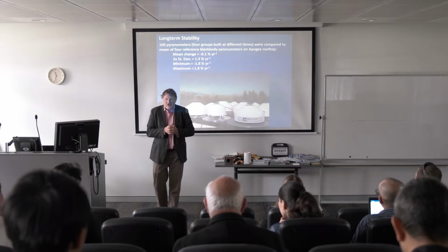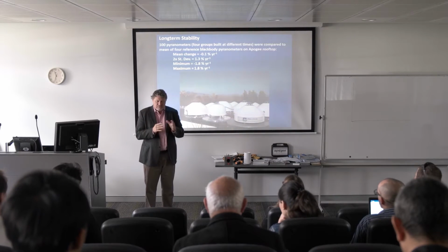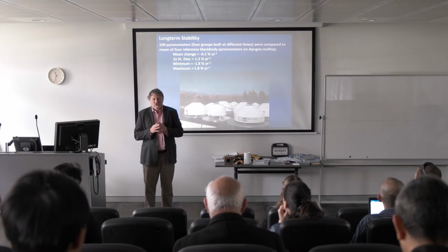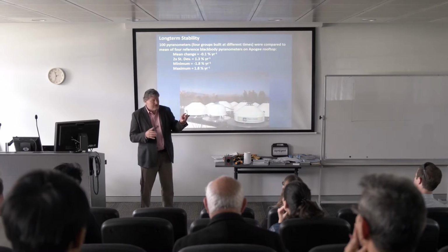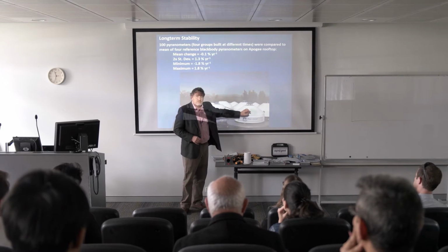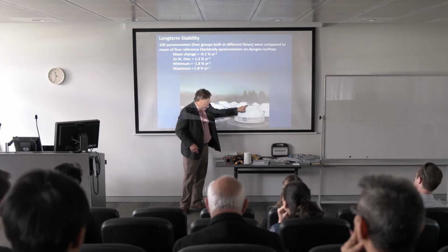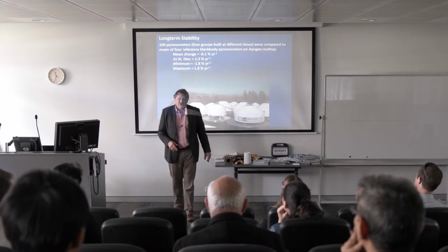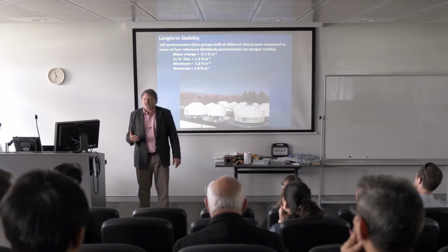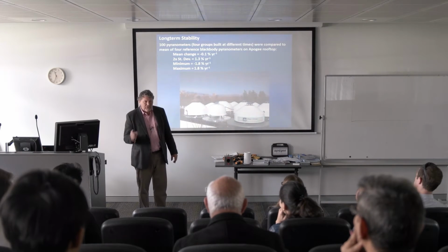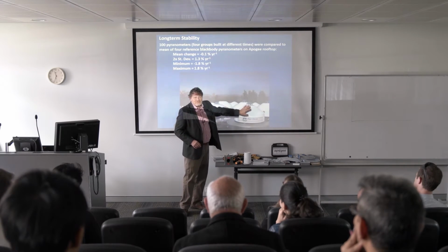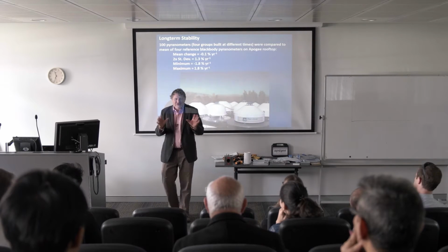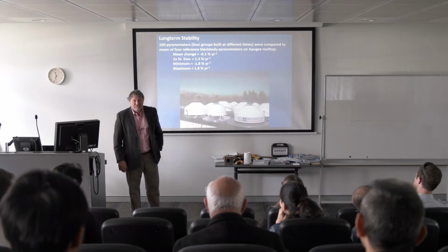So we go to a conference. We've been going to this conference in Brussels each year, a world meteorological conference. Kipp & Zonen doesn't have that little disc with desiccant anymore on their sensors. Doesn't that keep your sensor dry internally, so you never have condensation? They said the biggest source of leaks in our sensor was that port, that little desiccant port. And so we just took it out, and now we have a better sealing, and it's dry when it's manufactured, and we hope it's going to stay dry for many years.